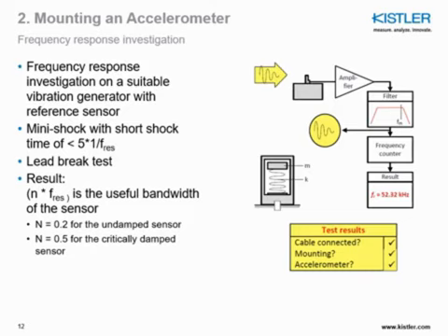So in each case, it's very useful to really investigate your own mounting configuration with your own sensor and your own mounting base and run a frequency response test to understand your resonance peak, and then consider that basically your frequency response plus or minus 5% will be somewhere around 25% of this first resonance peak value. Now, in the investigation I showed before, we were using a shaker.